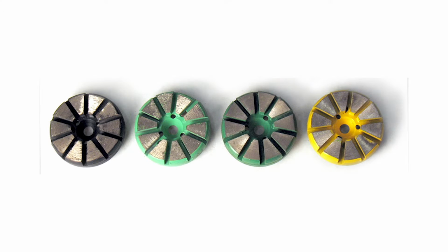If it's specified as, for example, a CSP 2, concrete surface profile 2, generally speaking, in terms of what's accepted in the industry, that is a diamond grind. The substrate, the concrete hardness, and then the variation of diamond tool that's used is going to greatly influence that so-called scratch pattern. If it's a 16 grit, if it's a 30 grit, whatever grit diamond it is, the way that the substrate is going to respond has a lot to do with its hardness and its natural makeup. So scratch pattern doesn't really factor into a profile conversation, but there is something to be said for the trails or the marks that are left behind after diamond grinding.